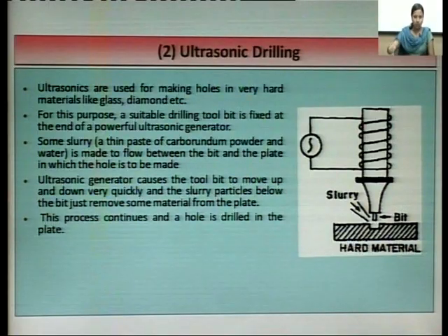Ultrasonics are used for making holes in very hard materials like glass, diamond, etc. For this purpose, a suitable drilling tool bit is fixed at the end of a powerful ultrasonic generator. A slurry, or thin paste of carborundum powder and water, is made to flow between the bit and the plate in which the hole is to be made.